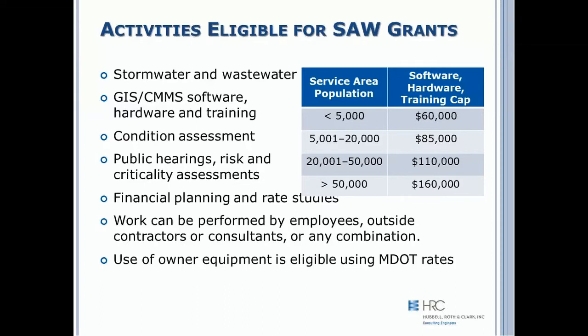You can perform condition assessment, which might include cleaning and televising of sewers, PACP pipe rating, structural evaluations, or other types of physical assessments of condition of your assets. Eligible costs also include the costs associated with public hearings and risk and criticality assessments. Financial planning and rate studies are eligible. And the work can be performed by either your own employees and staff, outside contractors or consultants, or any combination